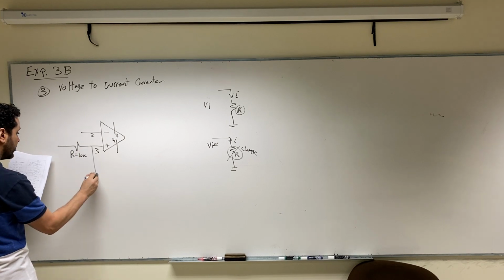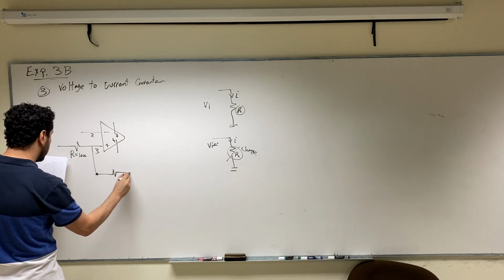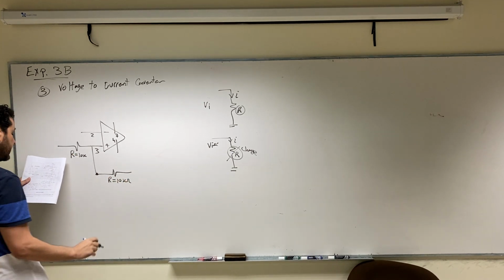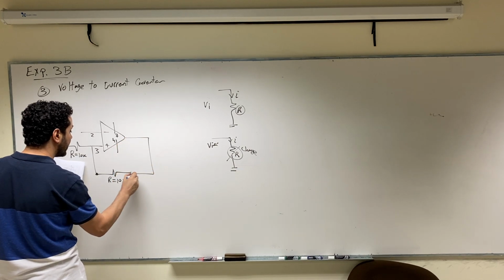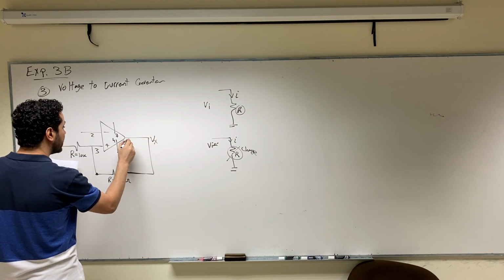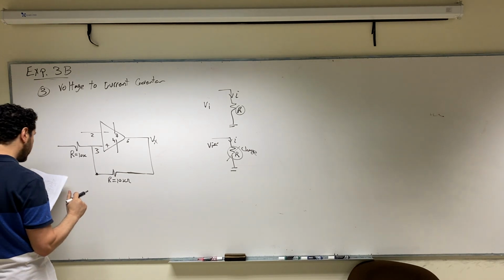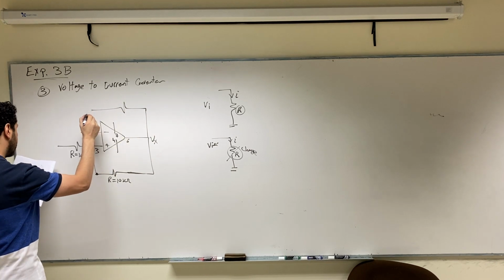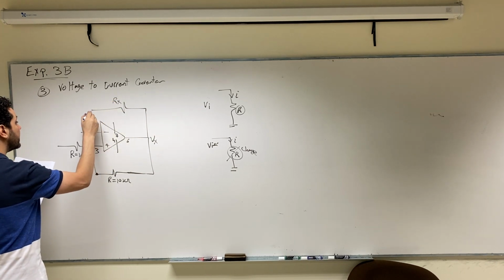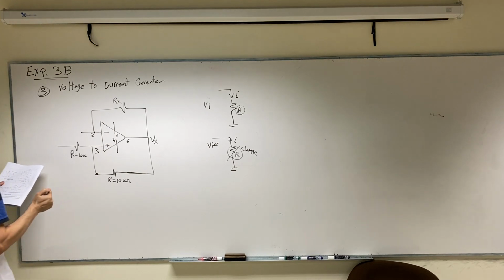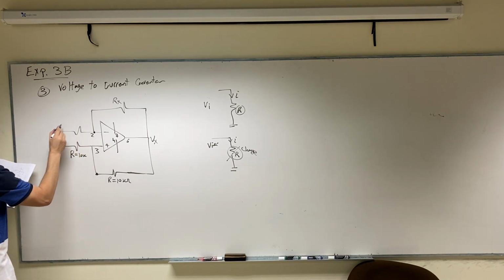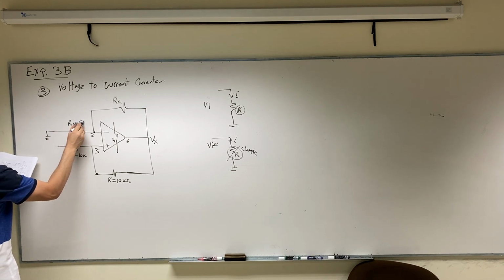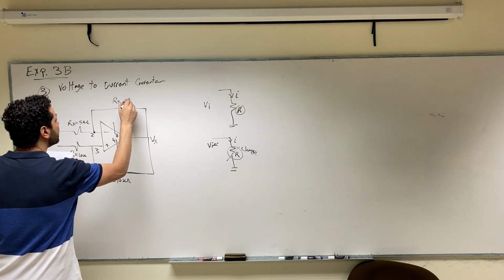And here also we are going to connect R, 10 kilo ohm, same resistance exactly, and then connect it to terminal number 6, which is the output. Then here Vx will be connected using a resistance Rx to terminal number 2, and then here resistance Rx connected to ground. And Rx here we are going to use 5 kilo ohm.